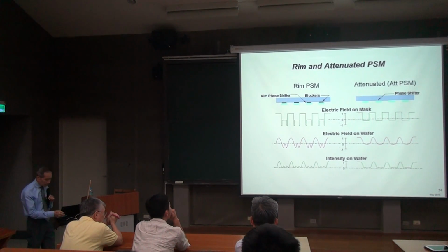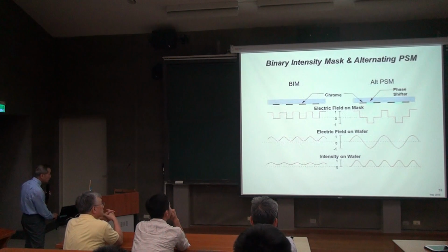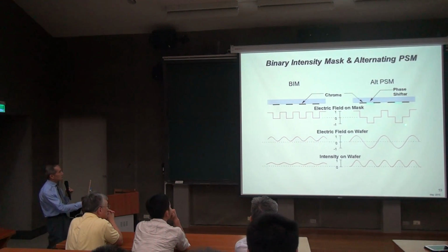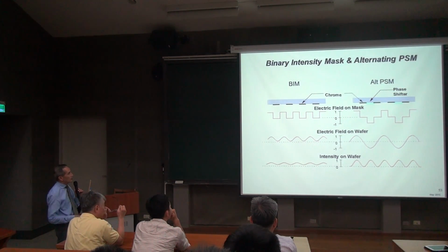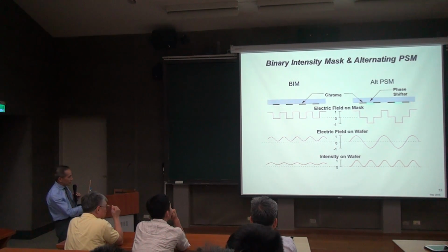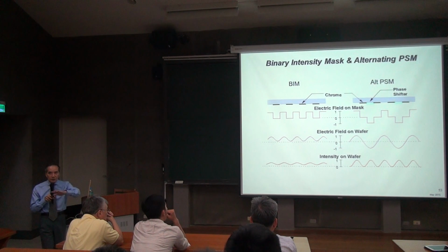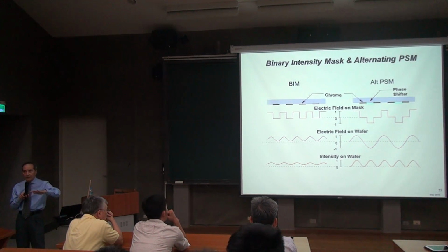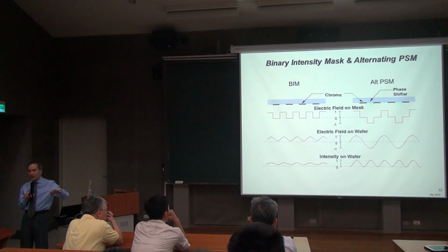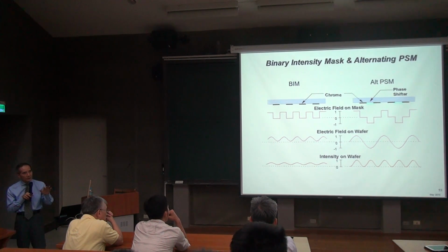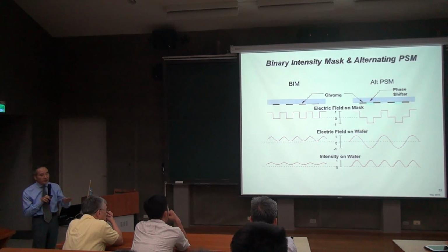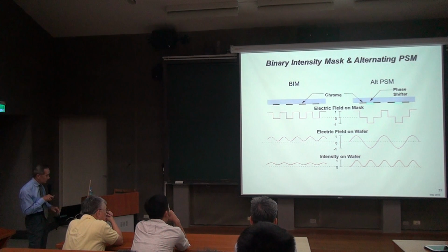Okay, that's another type of phase shifting mask. This phase shifting mask is very powerful. It's called a strong phase shifting mask. The problem with a strong phase shifting mask is that you have restricted every other element. And when you are dealing with a two-dimensional case, you cannot arbitrarily shift phase alternately. You run into phase shifting conflicts. Okay, then you have to deal with that.